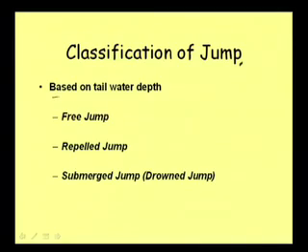So, one classification of hydraulic jump that we carried out is based on the tailwater depth. And proper understanding of this particular classification is very important. This way we classify the jump as free jump, then next is repelled jump, and then we talk about another jump which is called submerged jump or drowned jump.